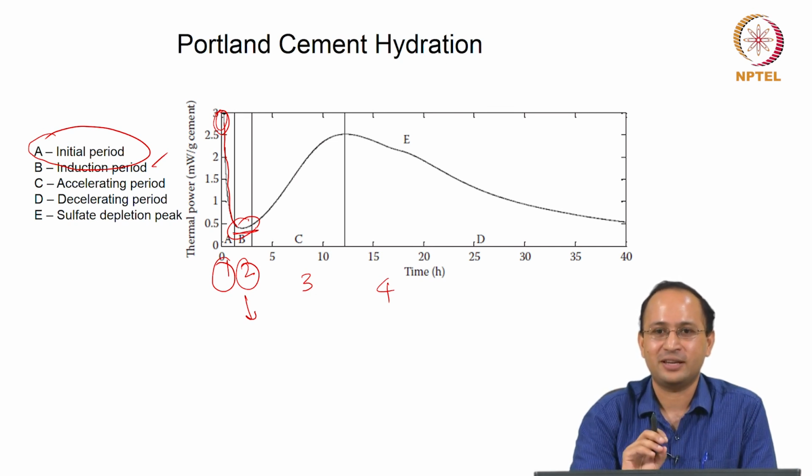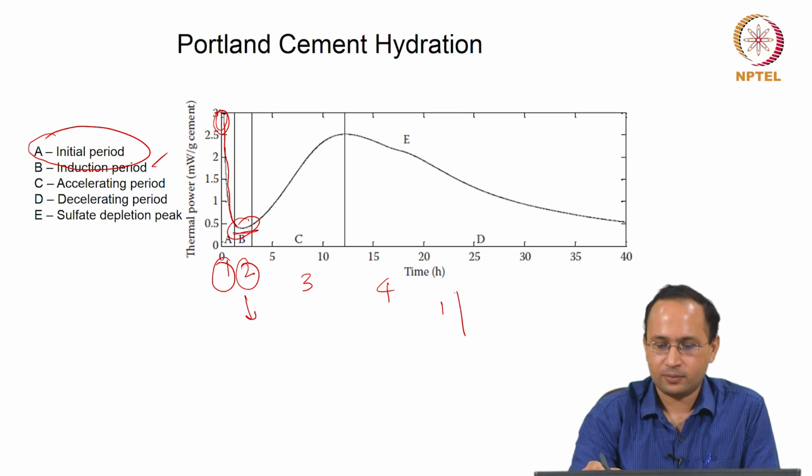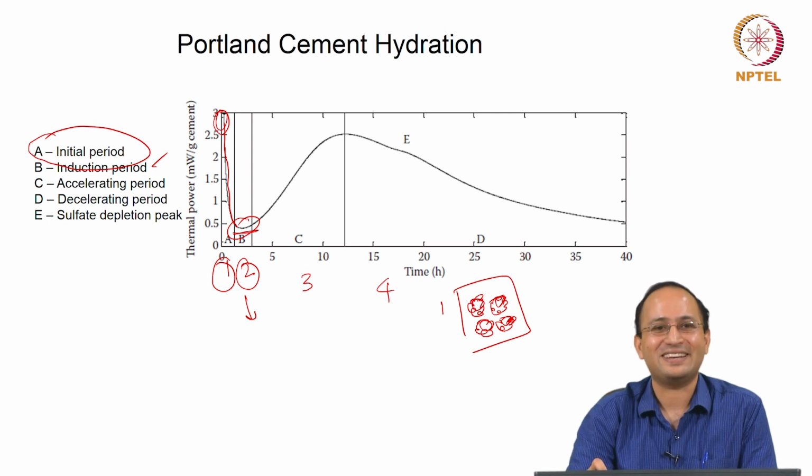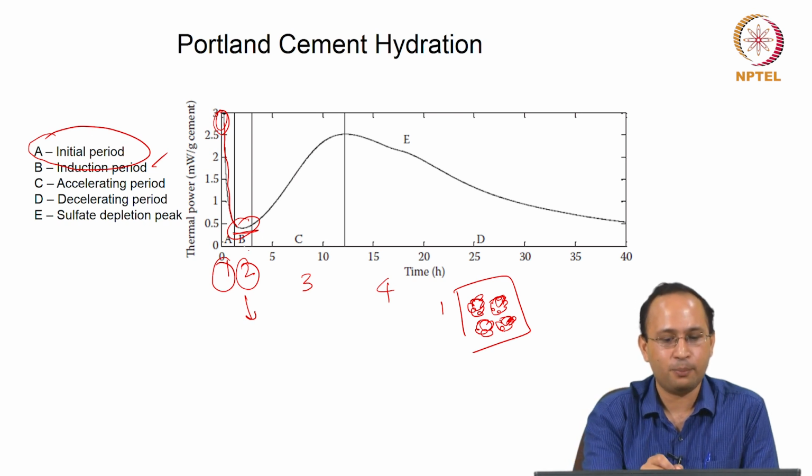So imagine you have these cement particles. Now after some time you form something on the surface, right, that acts as a barrier, right. You have water, then it acts as a barrier for some time, right, but after some time this barrier breaks down, right, but it gives you some time to finish your concrete, for an example, or maybe transport it. So it is very important. So induction period, right. Then what happens?